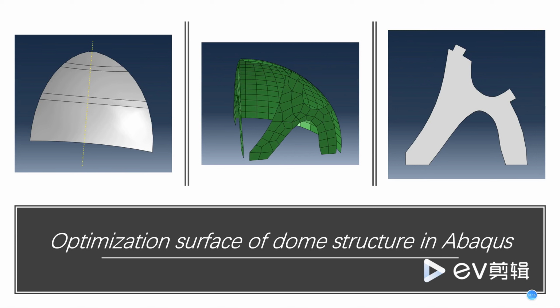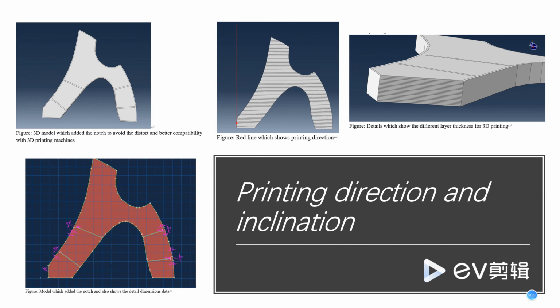Its optimal topology is used to create a 3D model for 3D construction printing from the results of Abaqus. For the size of printing nodes, 0.2 meters is used for 3D printing, and 2 printing directions are also considered in this design. To achieve the maximum structural efficiency, the local geometry is optimized in terms of reduced maximum tensile stress at the expense of maximum compressive stress, with a comparison of stress levels. This process is called material anisotropy.